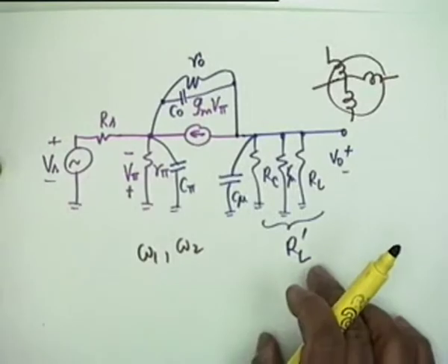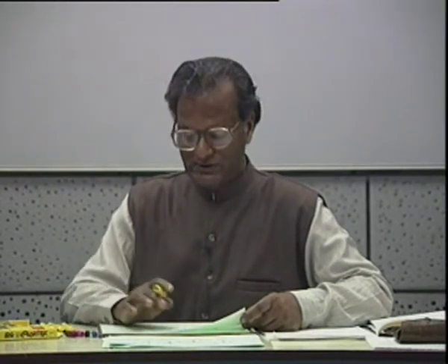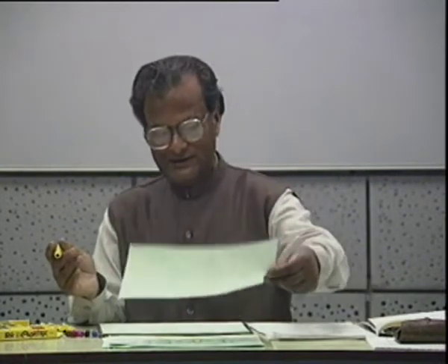Absolutely simple. Now, I don't blame you if you did not ignore. I have given you full credit. But in practice, if this was required to be designed, then you better do that. Otherwise you will require a SPICE program, or you have to write a program, and writing a program costs engineer time. After all the exact calculations, you will have to change resistances anyway. So rough approximations would be all right for omega 1, omega 2, and then the question of design.